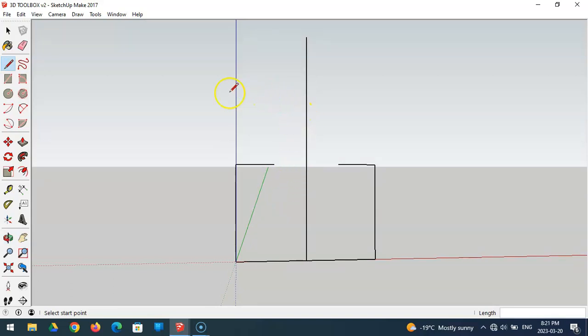Now, grab the circle drawing tool and click on this top point. Once you've clicked on it, you're going to move your mouse, and you can see the little red line show up. It doesn't matter which way, actually. It doesn't have to be red, anyway. And it's asking what the radius. If you look in the bottom right corner down here, it says radius. What do you want the radius to be? You can pull this out as far as you want. It doesn't matter. You let go of the mouse, and then you type in 20 for radius. And it'll make a little 20 radius circle.